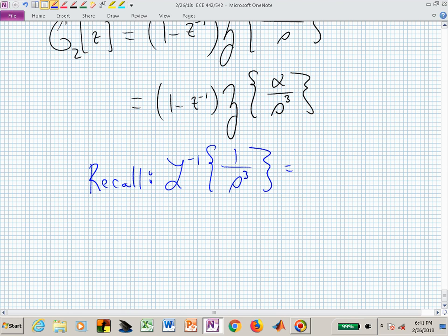Now what happens when we inverse Laplace transform 1 over s cubed? t squared, but we actually have a factor of 1/2 sneaking in on us. It's actually 2 factorial, but 2 factorial is 2, so it's really just 2. But we now have t squared over 2 as the inverse Laplace transform of 1 over s cubed. So that's now what we have to sample and then z transform. So now we have this parabolic in time that we're sampling, and we want to then z transform that sequence after sampling.